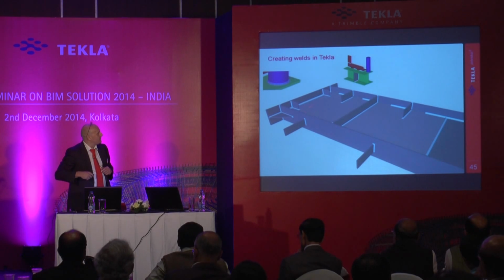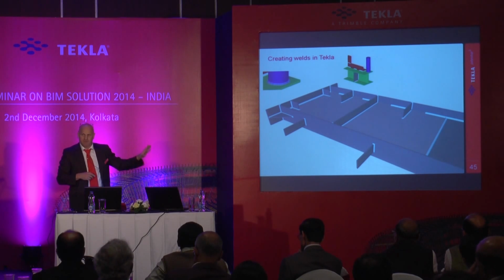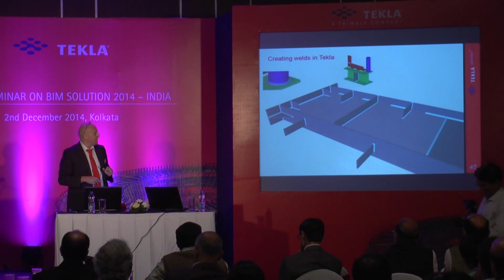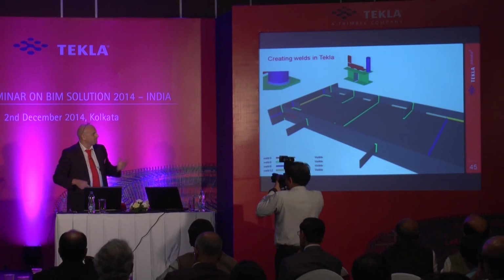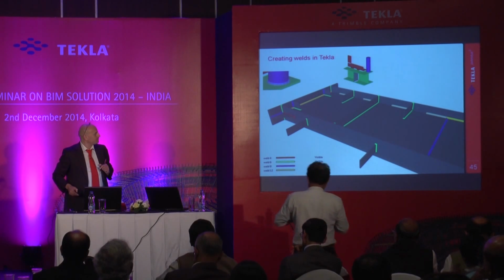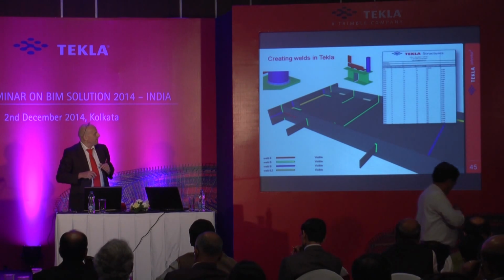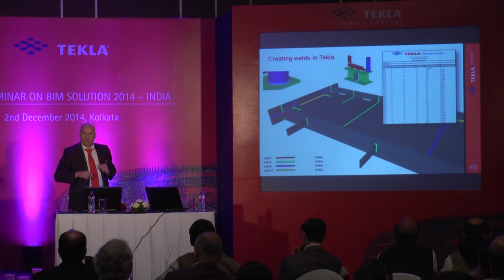Again, you've got the welds in Tekla. We've got new functionality that came out in version 19 and version 20, which allows us to model real welds, real weld weights, absolutely accurately, complete with all preparations and everything automatic. Beautiful functionality. And again, you can color code them to get the different ones here. Typical kind of Tekla stuff. Again, you get the lists for your surface areas, weights, welds, and volumes of welds for the project.